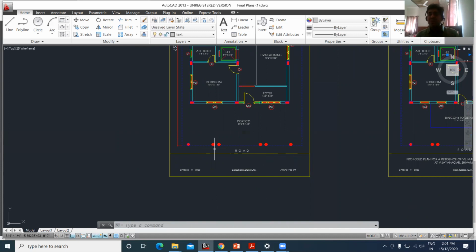Because of that, we have to get 18 footings. Just in case it is a combined footing, we are going to get 2 or 3 footings less. Let us say these two columns, if I make this a combined footing, then only one footing is going to come here. All those things depend on the structural consultant, how we have designed it, right? So we'll try to see that now.